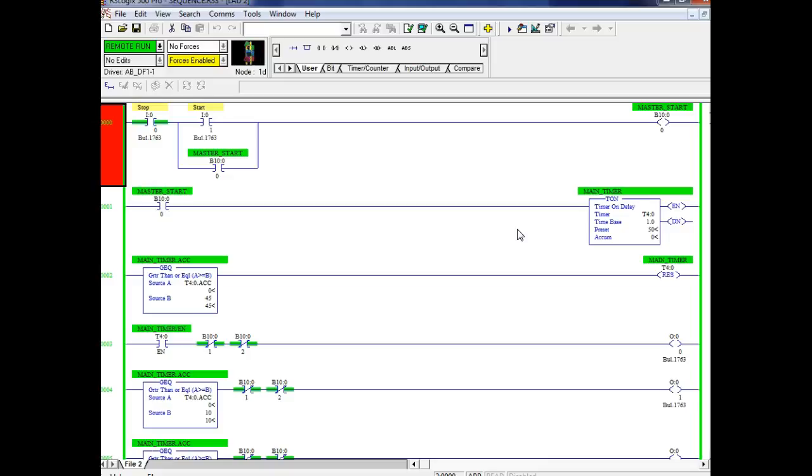This is the way we do a master switch right here. Anytime they say a master switch, we're going to use a master stop station. It's also called a 3-wire control, also called a memory circuit. That means nothing happens until I do what? And then we start it with a push button that they call on. They call it green.